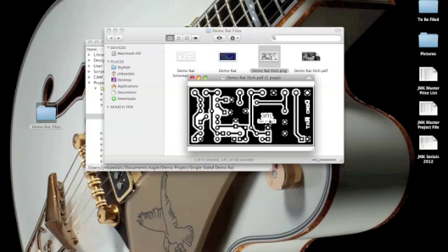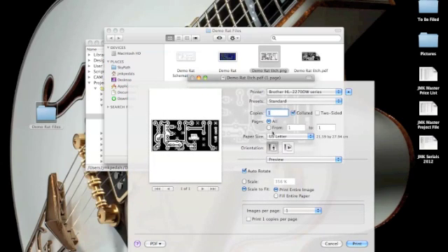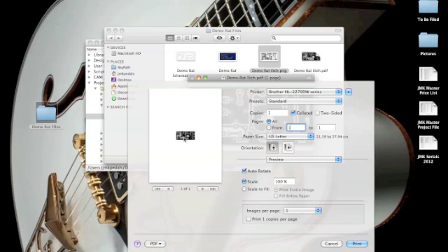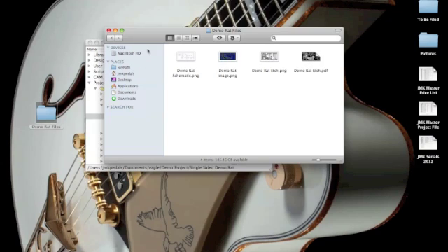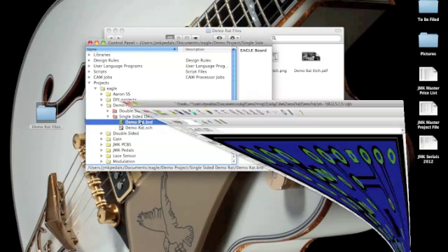Now, I could print this out, Apple P, and I'm going to tell it not to scale to fit, to scale it at 100%. See there? Just print that out. And you can always double check, right? Because you have your measurement. Is it 1.075 inches by 2.25 inches wide? Well, usually you just check the width, 2.25 inches. Is it 2.25 inches wide? Then we're good to go. Alrighty, and that is how you export a single-sided layout like this one here.